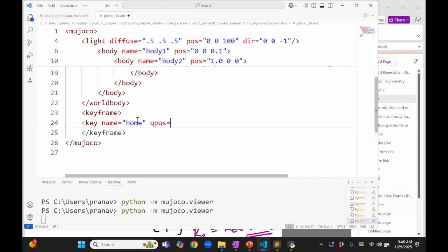And actually, all these commands which I'm saying are not just falling from my memory, it's just that I've used this with the documentation. I'll show you the document in just a bit. So we can specify the start position of the joint angles. By default, the angles are 0, 0, 0, right? But let's say that we want to change the first link to be at 90 degrees. So 90 degrees is 1.5707, so pi divided by 2.